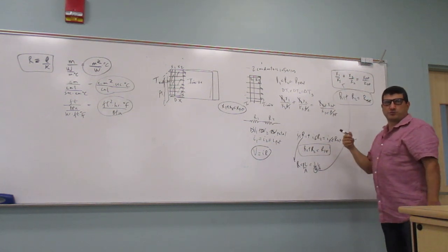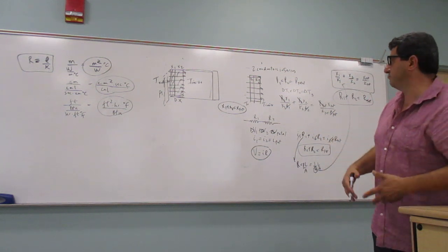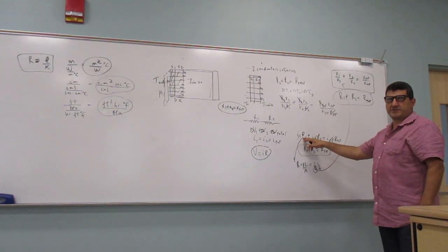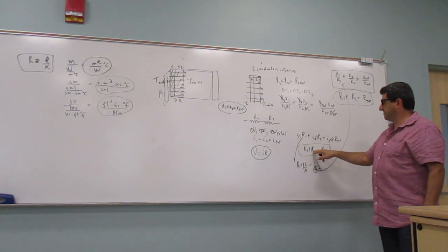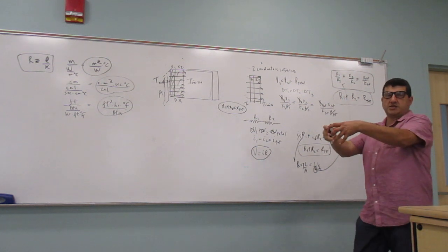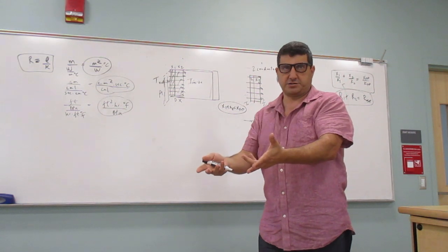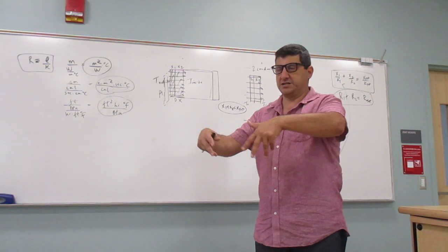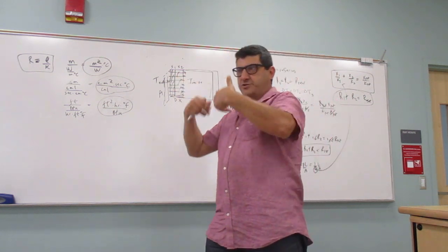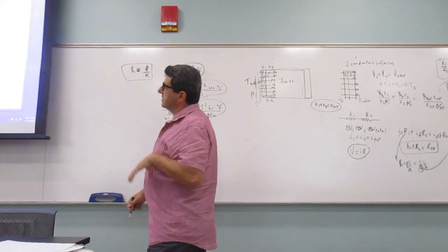Oh, so one of the reasons for defining R that way is it just makes it more like the electrical resistance, R. You see? The heat resistance adds up. So if you have two heat insulators next to each other, they're going to become better insulators. Insulation is going to add up. But conductance is going to decrease, the opposite. You see? So that's what they're saying.